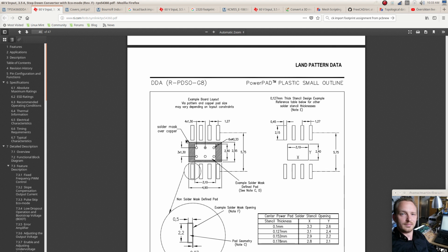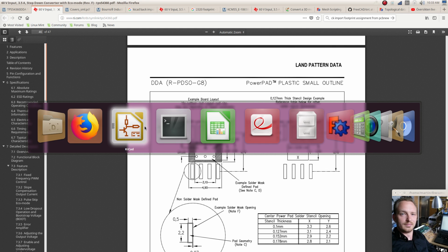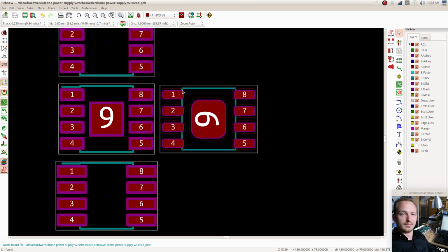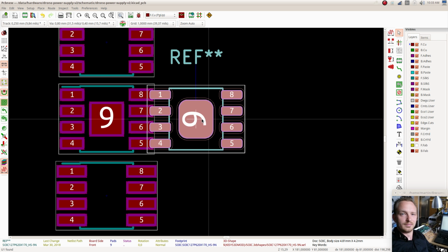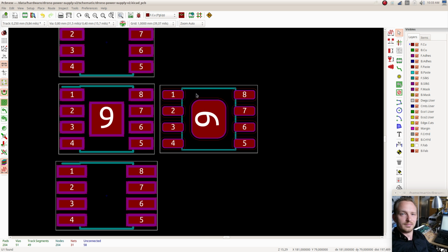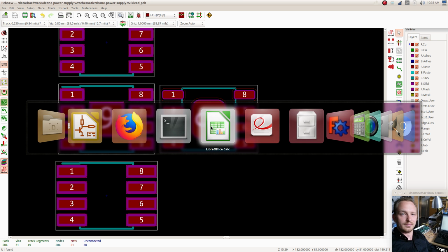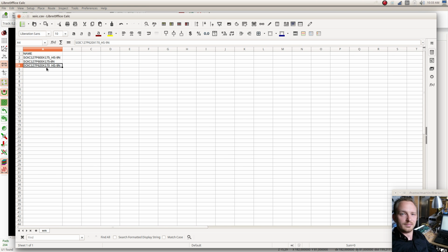But it doesn't actually have the silkscreen around it, so it's really hard to tell if this is correct. But according to the datasheet, it sticks out about, I think, 0.5 millimeter on each side. But this is close enough, and this is much better because all I had to do to generate this footprint is just type in a simple description of it, which is well defined, right?